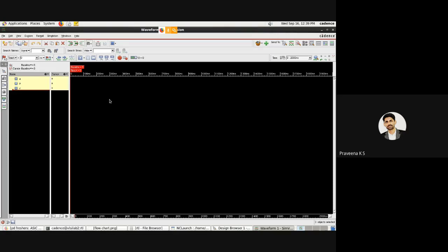So now we have to set the simulation time to check the simulation. First we have to set the simulation time for how long it has to do the simulation. Then we go for simulation. So how to do that is here. This small run icon is there. I hope it is here. If it is not, kindly zoom in and check. In front of that there is a small arrow mark. You have to click on that. If you click on that, it will ask for simulation time.